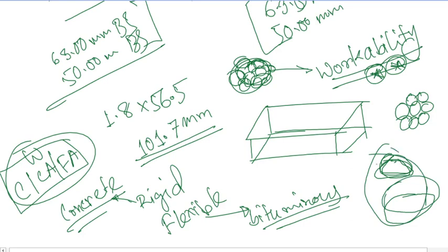You cannot mix this concrete properly with cement and coarse aggregate just because of these particle shapes. It will give you a less workable concrete, and in turn it will impair the long-term durability of the concrete. There is a possibility of cracking or shrinkage cracks whenever a rigid pavement is constructed using this type of aggregate.